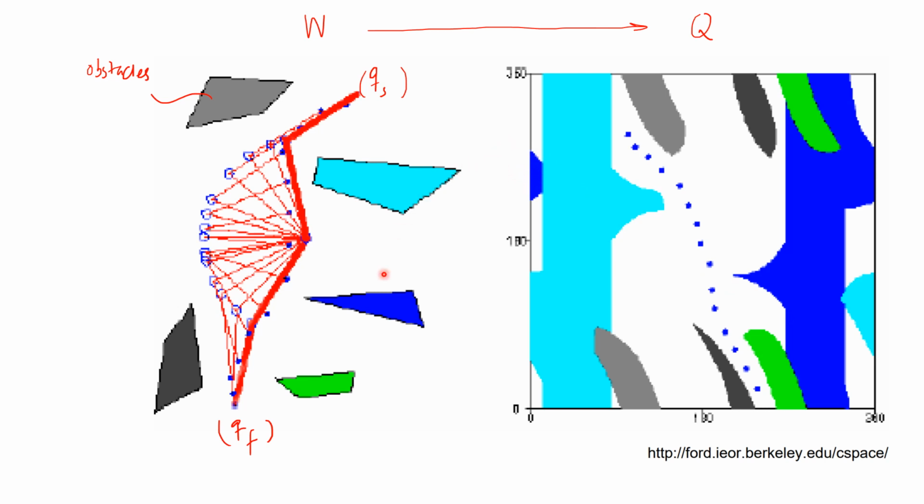So if there is a density of obstacles, the manipulator needs to find a way out of that dense population of obstacles, starting from the starting configuration and reaching the final configuration. That is, in this particular case, shown in the configuration space with these blue dots, and these are going to be the result of your path planning exercise. This is exactly what we need out of this exercise.